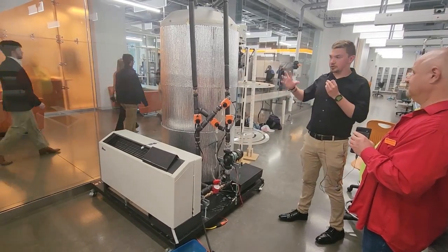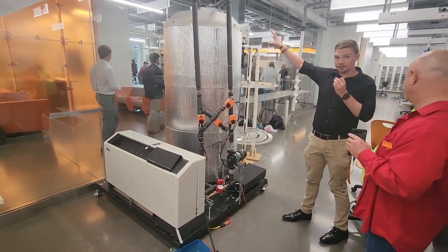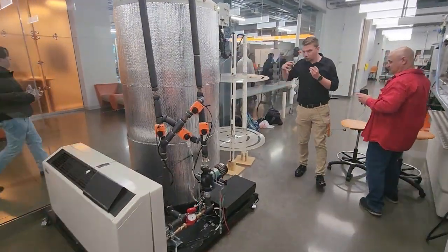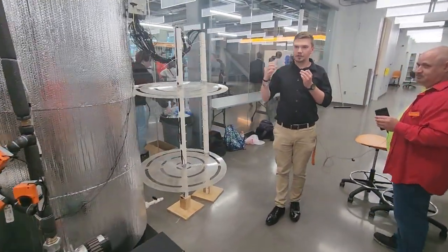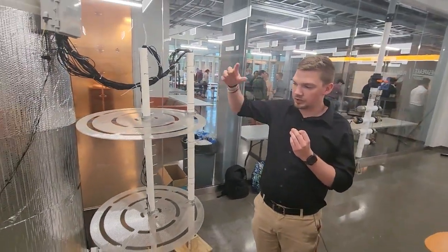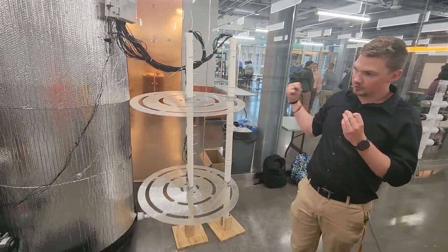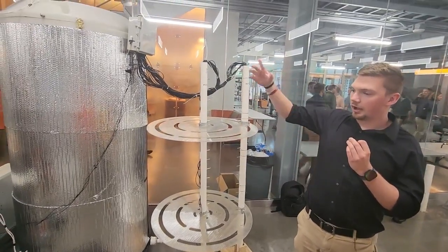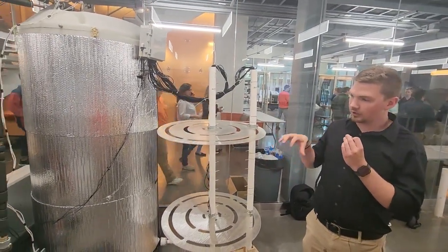We can do this through the use of diffusers, which we have in the tank right now, through baffles, which you can see over here, which normalize flow, prevent mixing of temperatures, and allow, as we're flowing and cycling water through this and pulling heat out to use to heat a space, the cold water coming back isn't mixing and bringing down the temperature of the whole tank.